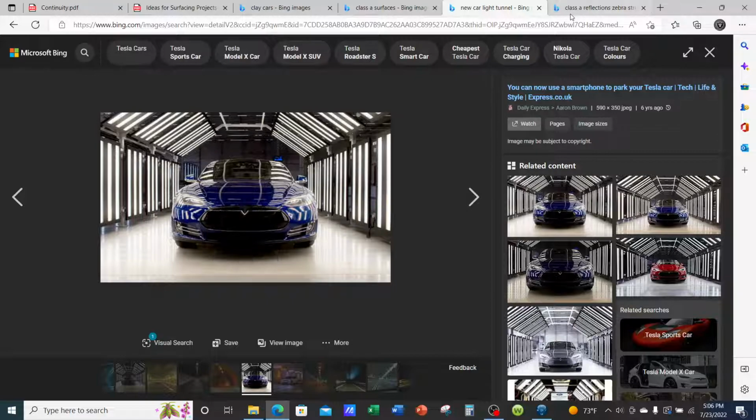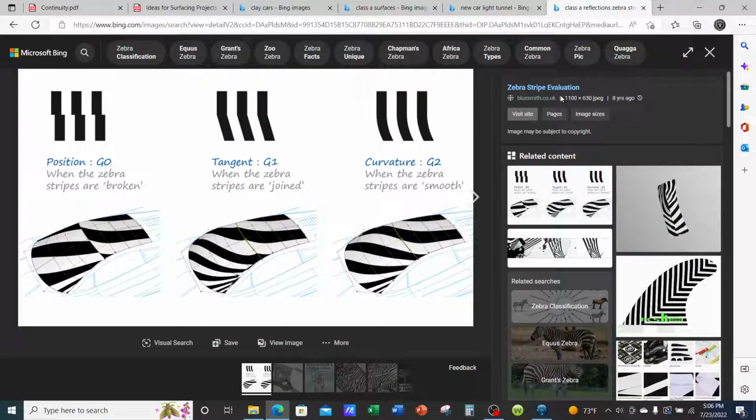Okay, so here's something I found online. I'm not going to take credit for this. Here we're looking at the rooftop of a car. Here's a windshield. Typically when you go work for a studio department in automotive, first thing they'll do is train you on how to create a rooftop surface, how to create from scratch a windshield surface, and then how to analyze it, right? Using curvature, porcupine curvature analysis, and also using the zebra stripes to reflect off of.